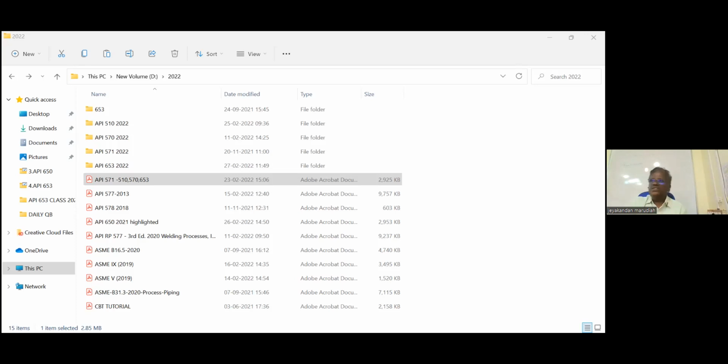So first I will start with the damage mechanisms affecting the outside of the tank. So what are the external corrosion damage mechanisms? Atmospheric is 1. Chloride and CUI are outside, 2. Then soil, these 3 are the outside corrosion. Okay, so let us complete terms and definitions, then we will go to these 3, then to the internal corrosion, then other mechanisms. So please take first terms and definitions.